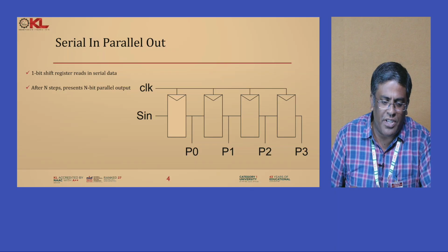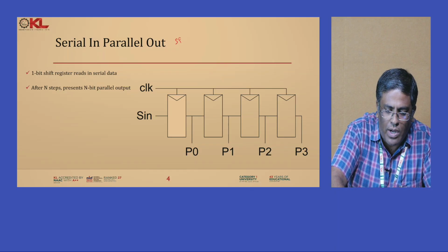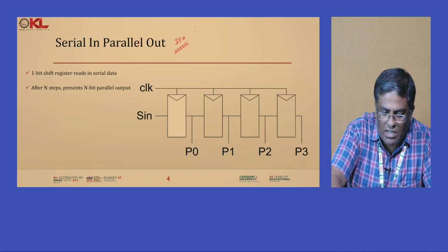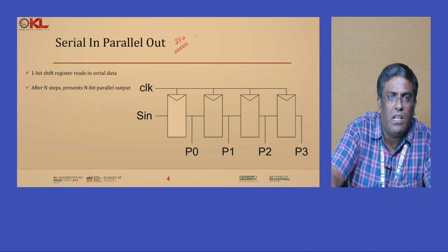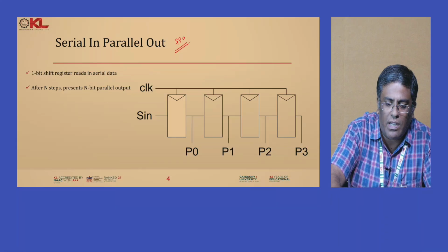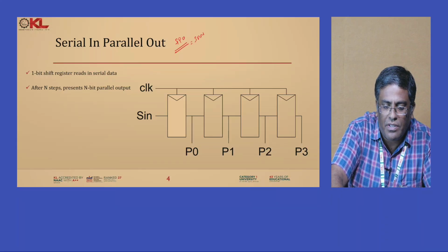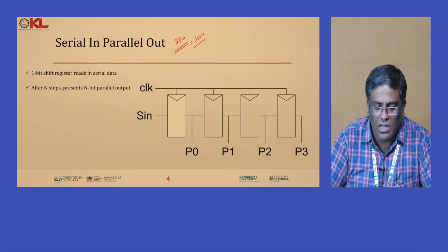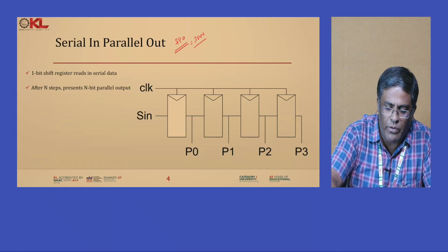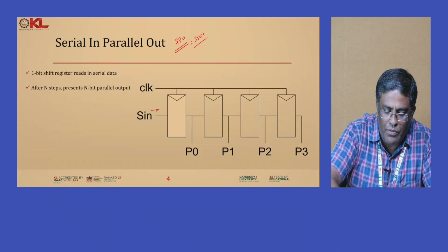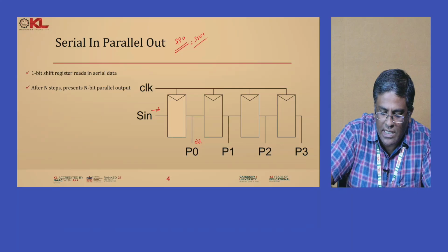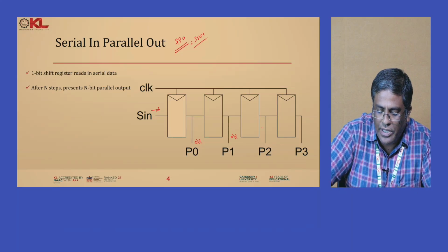As in the previous discussion, between SIPO and PISO, since SIPO provides higher speed of operation, we can use this SIPO as your SAM architecture, serial access memory architecture. As the name SIPO says, the data comes in serially over here, and the output is taken in parallel at all the registers at these points.